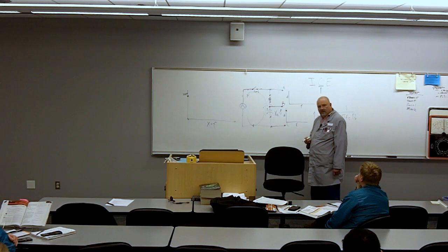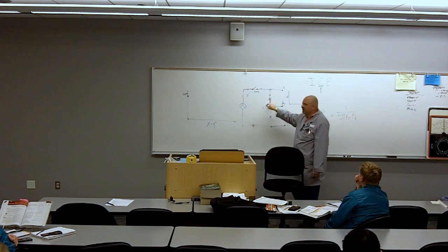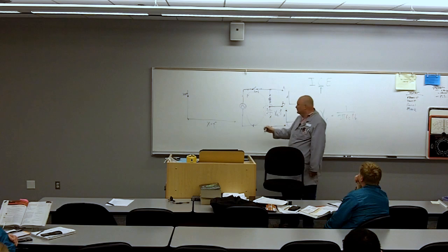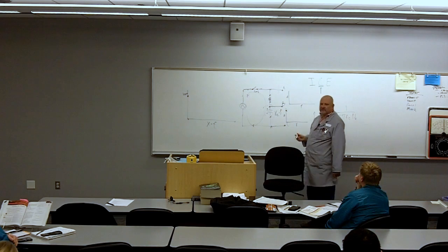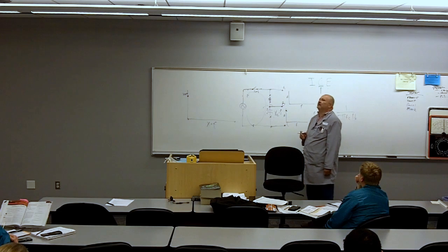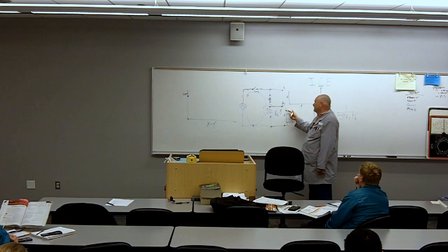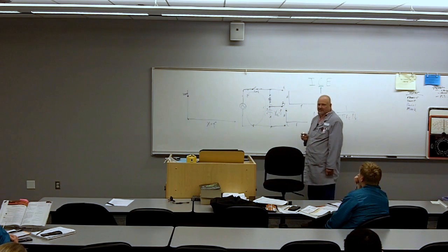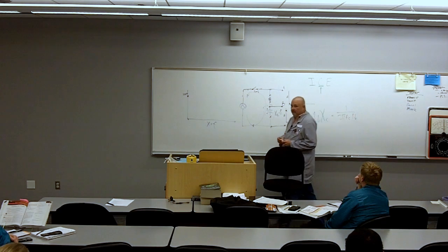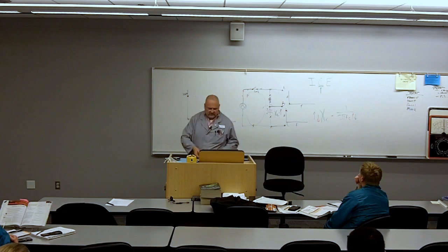Does that make sense? What kind of a circuit is this? Never forget that. This is still a series circuit. I got a big voltage drop here, what's my voltage drop across my resistor going to be? Because a series circuit is also known as a voltage divider. So if I got a big voltage here, what's my voltage across my resistor going to be? It's going to be low. Do you agree? Am I baffling any of you? Hopefully not. It's all straightforward. This is all stuff that we've studied.